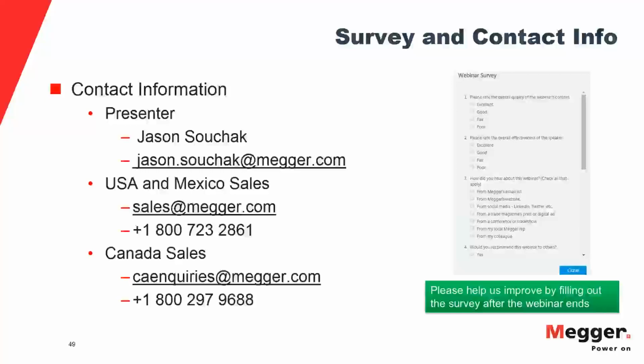There's nothing you can do about background noise. You just have to measure it and live with it. And if you're in too noisy of an area, you may not be able to do effective testing. But like I said, in my experience background noise can be as low as maybe 20 picocoulombs, about the lowest I've ever seen, up to about 150, which is about the threshold where we can do meaningful testing.